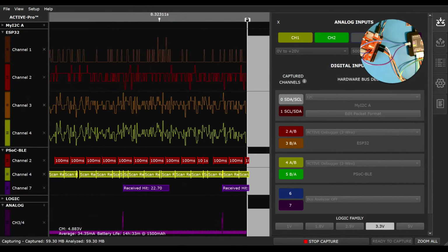If you look at this, and anyone who's familiar with current characteristics, this looks like a traditional 3-channel BLE transaction at the very end. I believe they're doing a Wi-Fi transaction at the front. Not quite so sure, although I'm sure I could figure it out. But these last 3 bursts at the end are definitely BLE advertising packet channels.